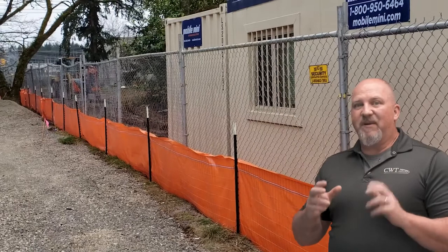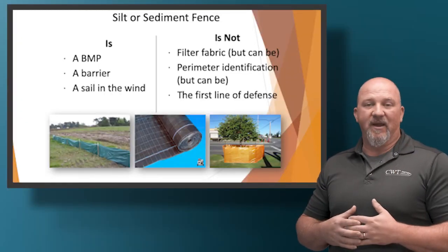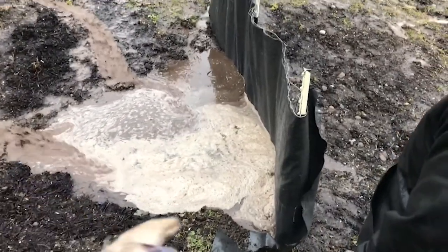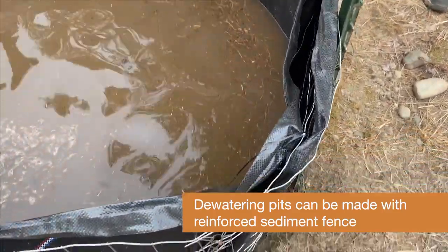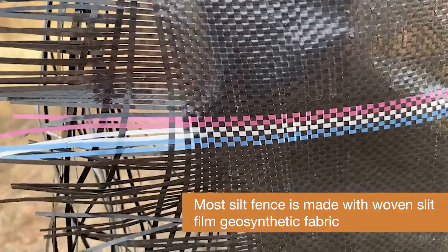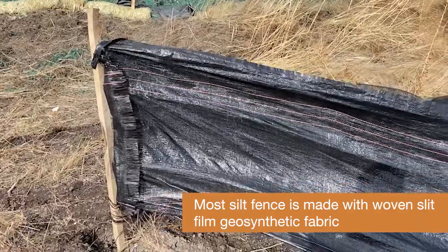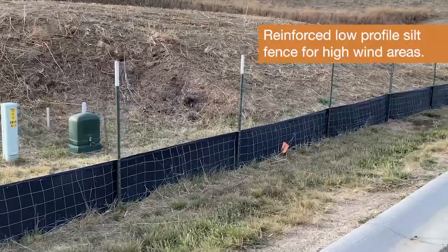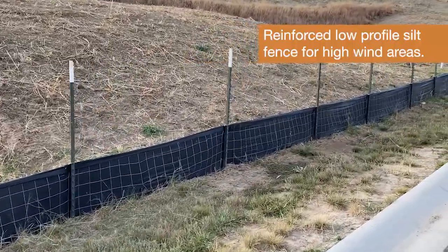However, a lot of people have had some challenges when utilizing it as a BMP on projects. It is not filter fabric. That is a misnomer unless you buy a very specific geosynthetic on the face of the sediment fence. It's a barrier. It's meant to be a separator. It's also a sail to the wind. And in a challenging wind environment, your sediment fence needs to be robust enough to hold up to that wind. Otherwise, it's going to rip into shreds.